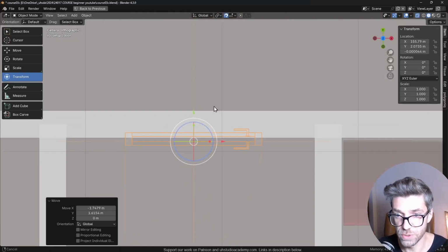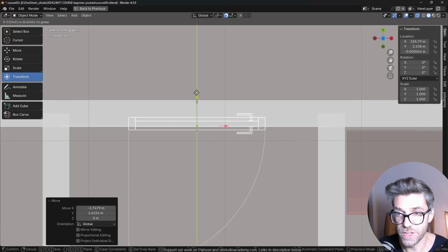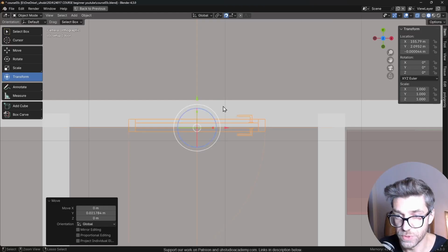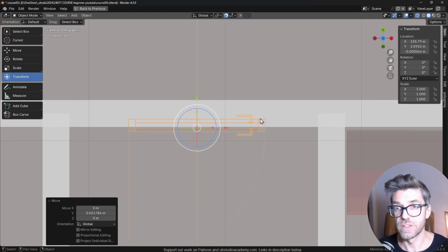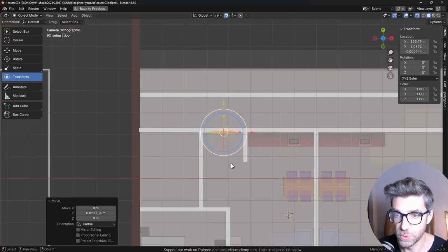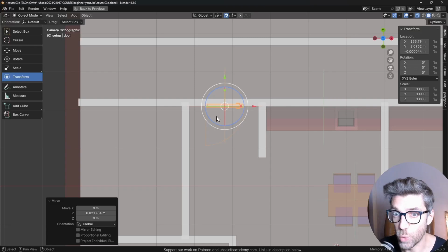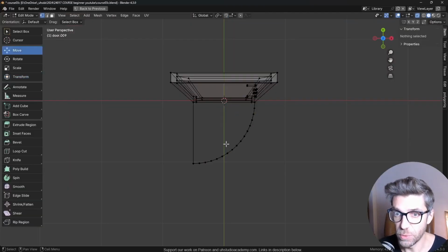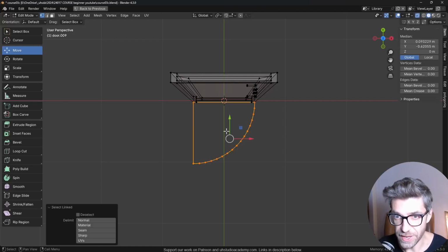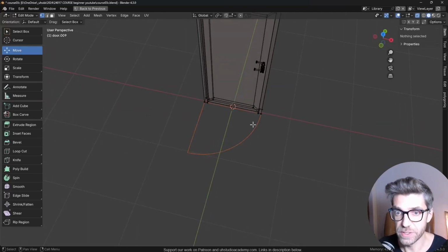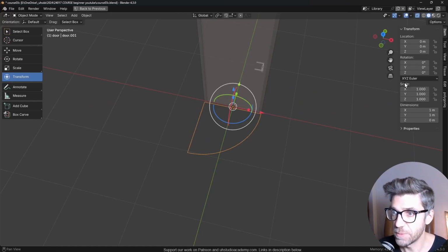And the way that I do these doors, so there's different iterations, right? So we can design a way for this, with the box, that it subtracts itself. But for the purposes of what we're doing here, we're not going to do that just yet. However, there is one thing that I would like to do, which is go into edit mode in here, go into edit mode here as well. And actually we want to separate this door element out. So P, separate selection. We're going to keep that as separate.